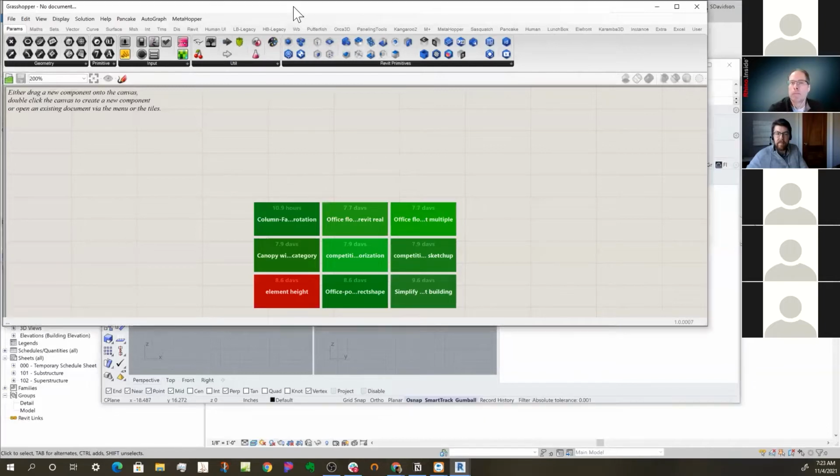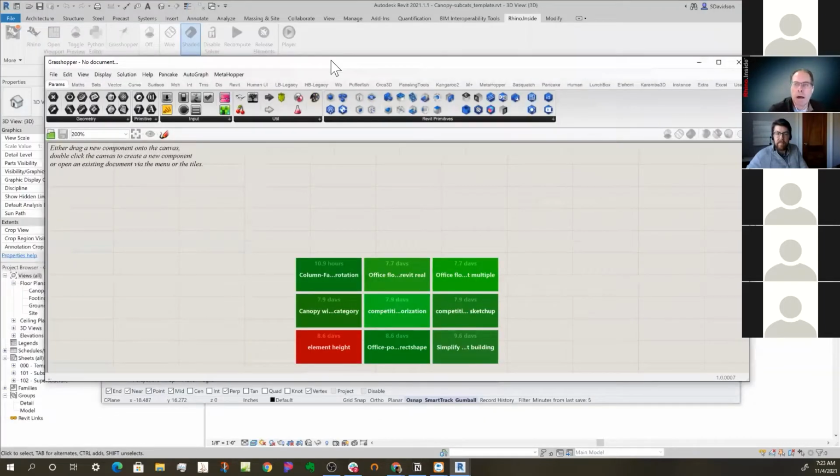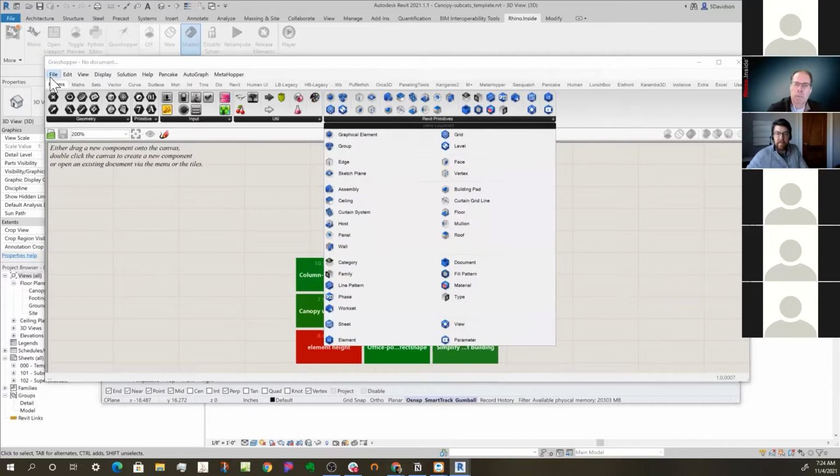So we have Grasshopper here. Based on your survey, many people in this workshop are really familiar with Grasshopper, so I'm just going to go over it really quick to look at the Revit piece of this. When Grasshopper loads inside of Revit, there is this little toolbar here on the params page, and these are all the data types, raw material pickers, all the raw params for Revit.